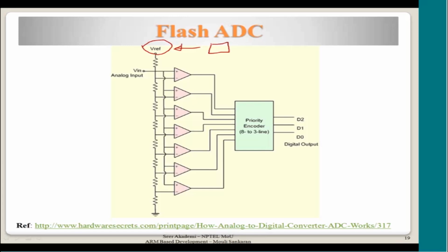Normally now we are trying to build ICs which operate at lower voltages, maybe 2 volts or 1 volt, where earlier it was 5 volts, and it has come down drastically because we want low power devices, so the voltage sources are also coming down in value. But as far as the ADC is concerned, there is a separate voltage source given, a more stable reference, which is called the V reference voltage. I will talk about this in the next slide.